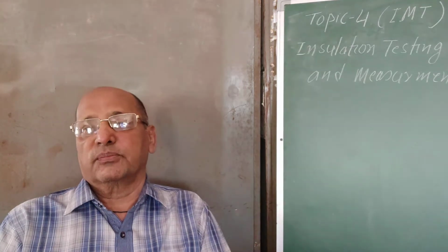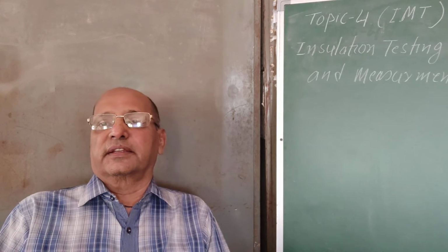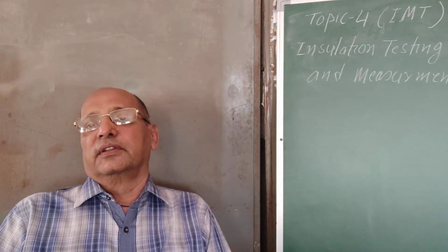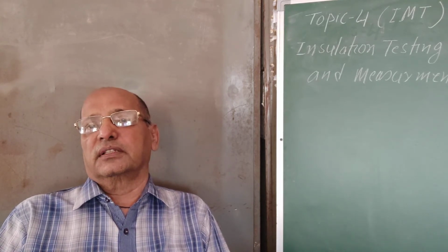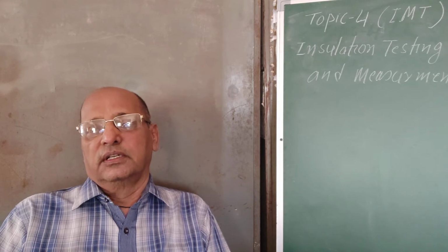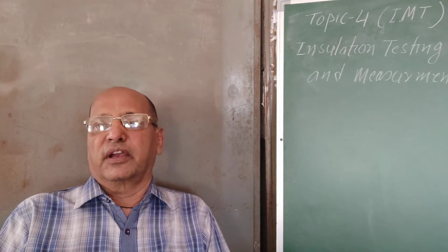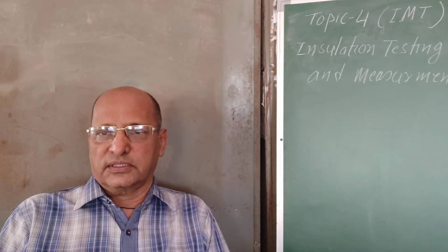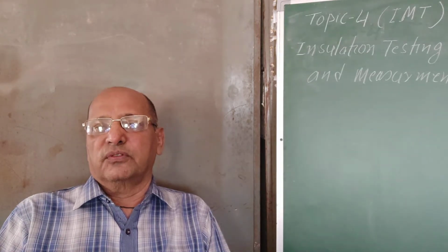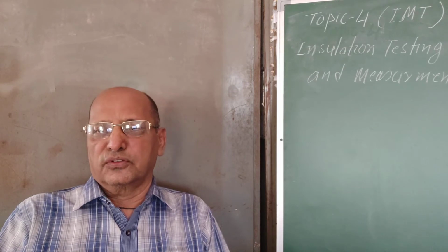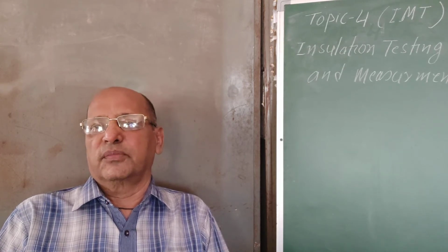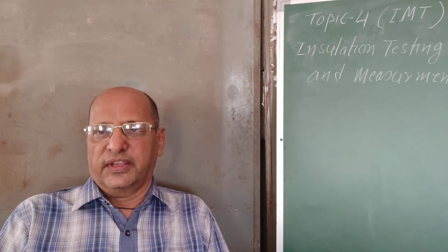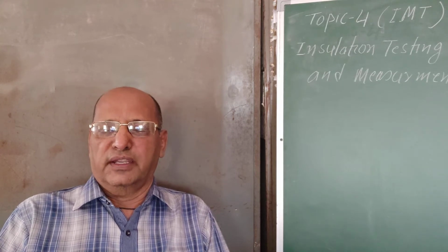Insulation normally provided in electrical equipment is PVC insulation. It is most popular for all types of internal wiring, industrial wiring and cables. Apart from PVC insulation, we also use cotton insulation for the winding of motors, fans and other types of winding.